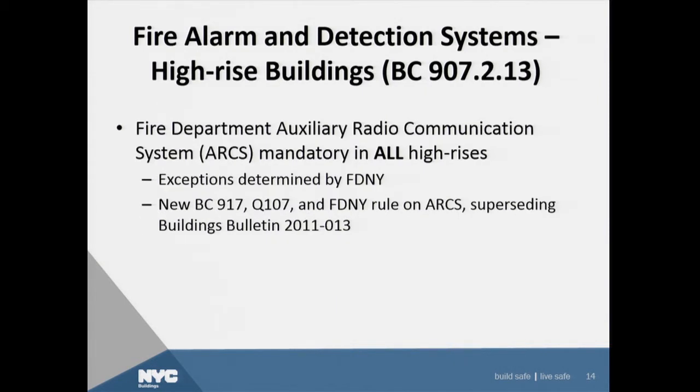Okay, so now ARCs. ARCs, you'll hear the fire department talk about ARCs. Auxiliary radio communication systems. These will allow the radios to repeat through the buildings. The requirement is that they be provided in the high-rise buildings. The fire department is working out their rules and how that's going to happen. They had issued a technical management bulletin on this explaining how that is to be designed. They are revising that, so I urge you, if you're designing high-rise buildings, if you are the fire protection engineer and you're dealing with these kinds of things, to understand what that means for your projects and follow up with the fire department on it. I've listed here the code sections that point you to it, and there you go.